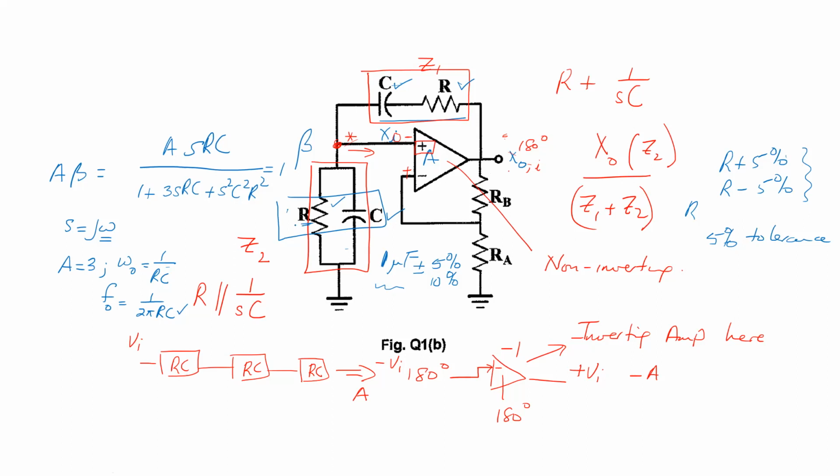The alternative would have been to start off with a particular value of R and then see what capacitor value you get. You have more options in getting resistors and getting capacitors. So if you had to pick one to start with, it is usually better to start with the capacitor.